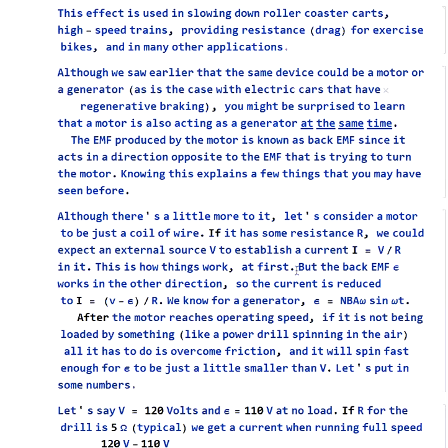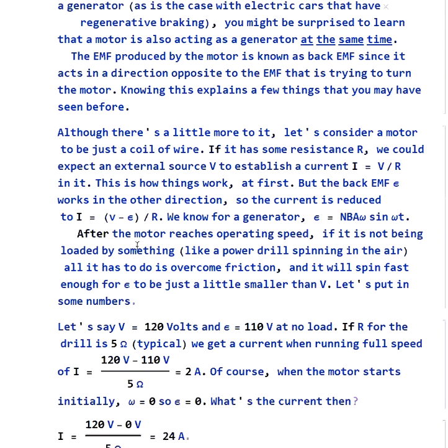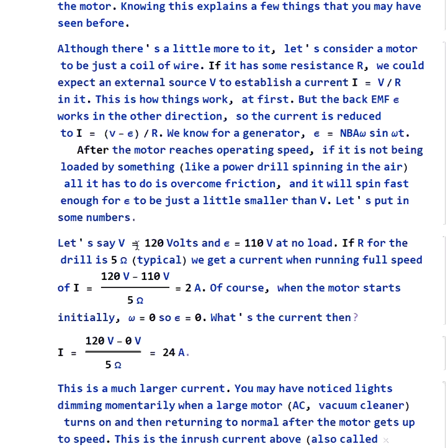So the EMF that the motor produces in this configuration is called back EMF, since it's fighting the EMF that's actually driving the motor. If you know about this, that'll explain a few things you may be familiar with. Now, to look at those, let's consider a motor to just be a coil of wire. It's not much more complicated than that.